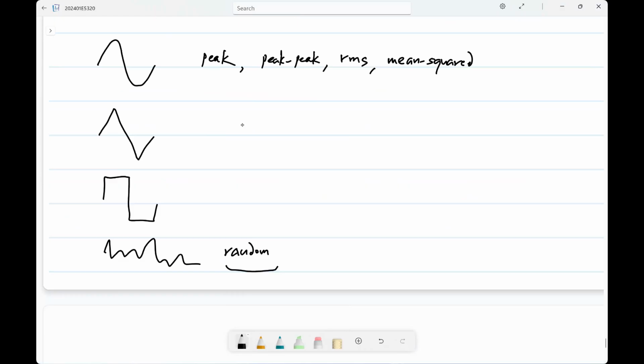No, in every one of them there is lots of information lost, because you are using one number to describe a signal that is varying in time. What is the peak to peak value of a Gaussian? Infinity. So it's basically useless, right? A Gaussian signal can be as high as infinity in principle, right?